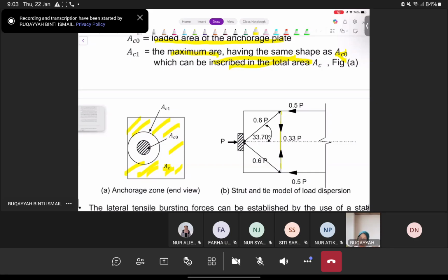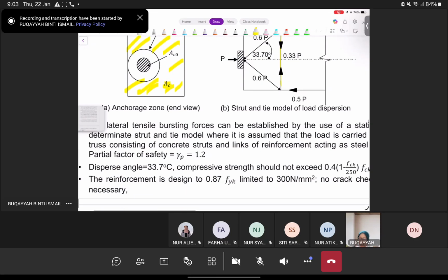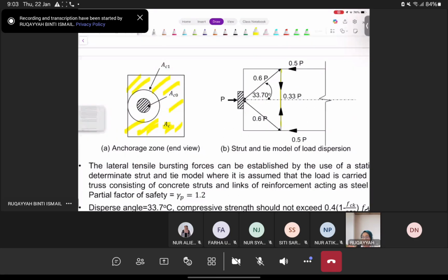All right. And what else? So you have this strut, where you take the resultant of the forces due to the forces applied by the tendon, which is horizontal. So it will spread into a triangle, in the calculation.